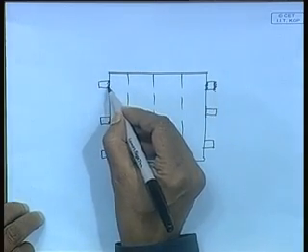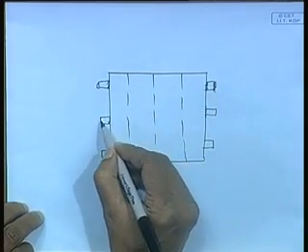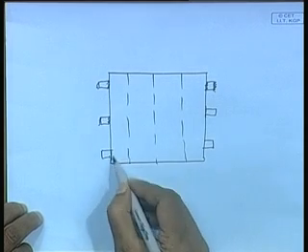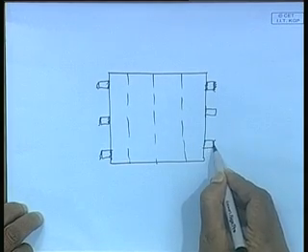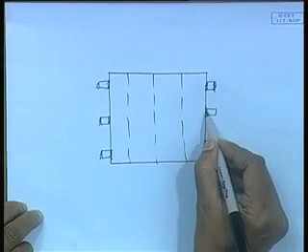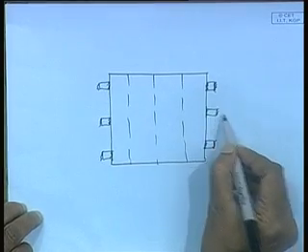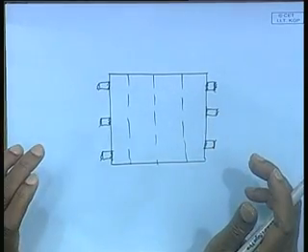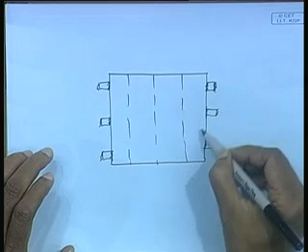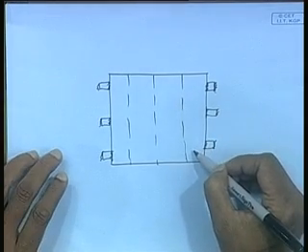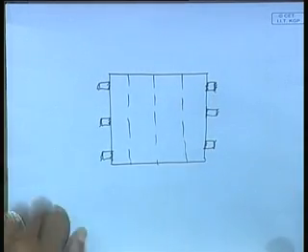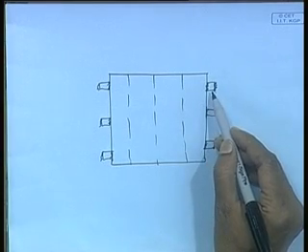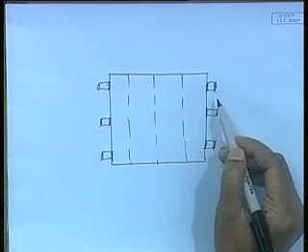When it is still hot, I weld it. So, what basically am I doing? It has to be done in a proper sequence. That means, one side you have welded to the plate, and before welding the other side to the fixed structure, I heat up the lug only and then weld it.